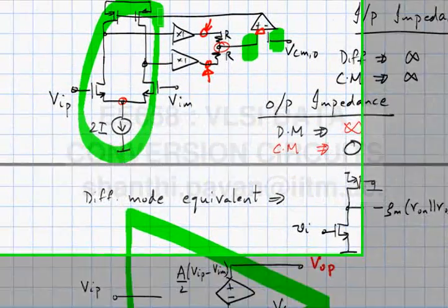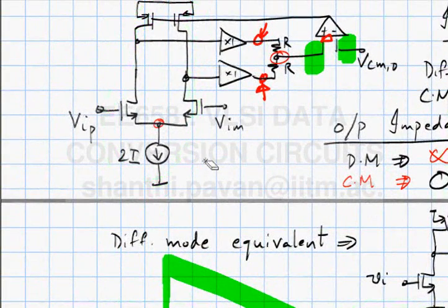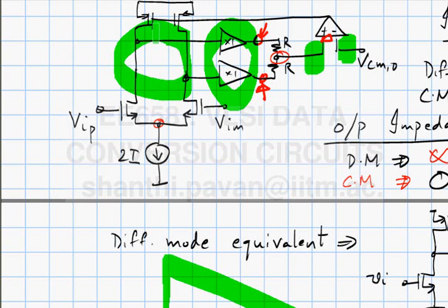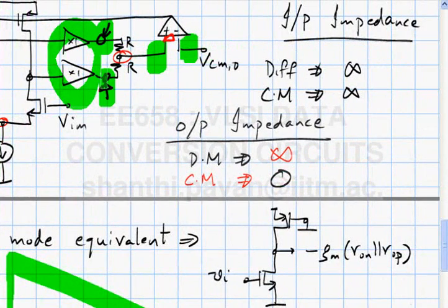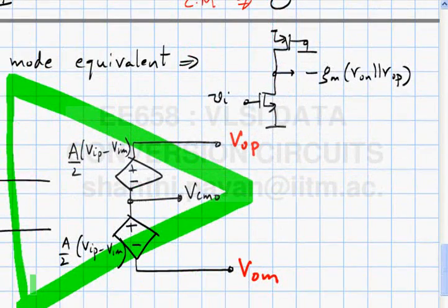So one way of retaining the large voltage gain but getting rid of the high output impedance is to simply use a voltage controlled voltage source at the output of this chap here, correct? This way you have both high gain as well as low output impedance. And if I treated these two as my outputs of my op-amp, then it will conform to this model. This is the macro model I've given you as the model to use for your assignments.